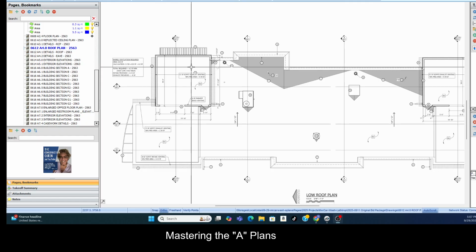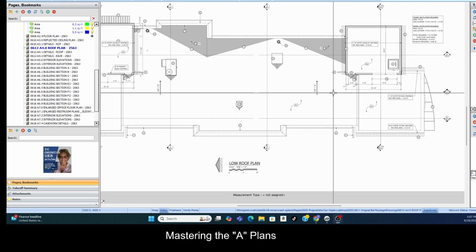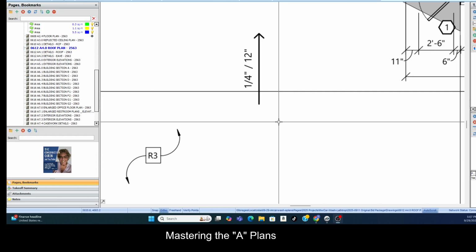And so we always have a couple things when we talk about the roof, because the roof is to have an angle so that water and snow and whatever rolls off of it. So you'll always see the pitch of the roof, and that means that it angles a quarter of an inch for every 12 inches.